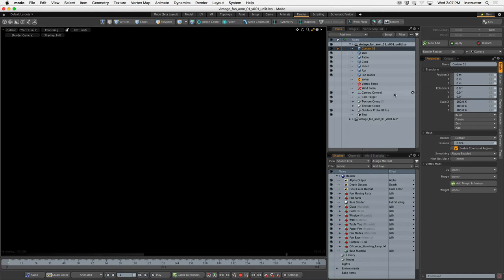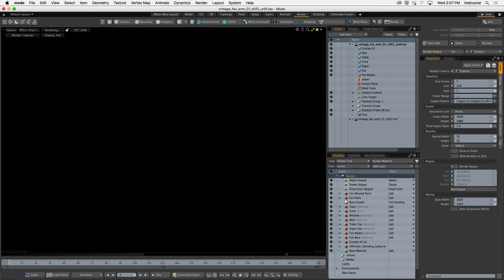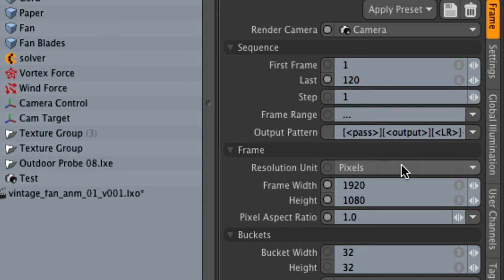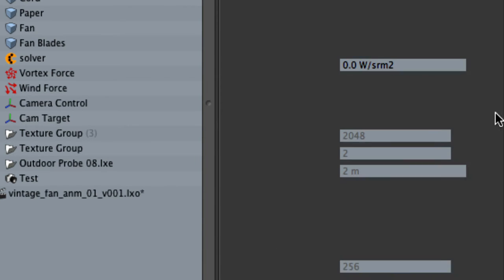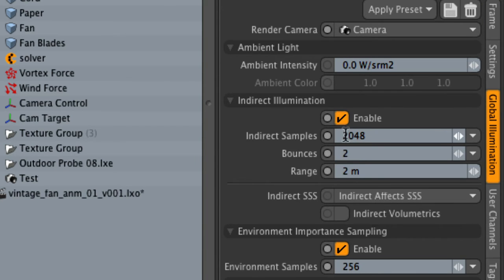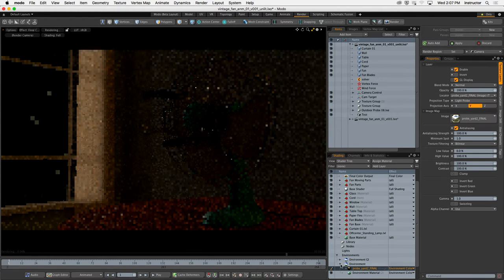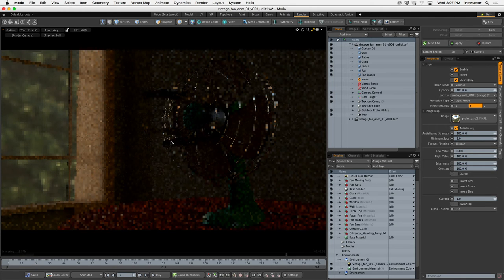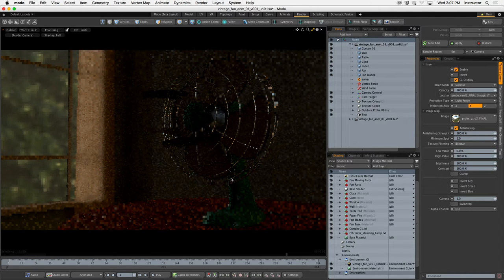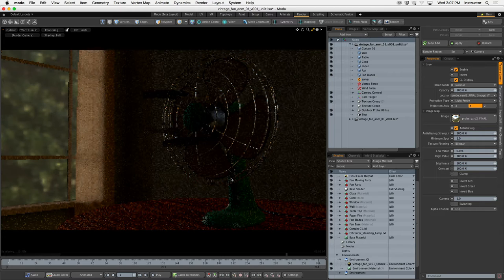The first thing that I always want everyone to do whenever you're rendering anything in the computer, I've selected my render item. Let's go over to the global illumination section and turn this off. Okay? With it on, and I've turned off everything here. Let me just activate my backgrounds. Okay, with the global illumination system on, this is what it's going to look like. Okay? Now, on the surface, the indirect illumination system is a helper, right? But it's a bad helper, and it's something that we want to consider at the very end, the conclusion of our rendering sequence.